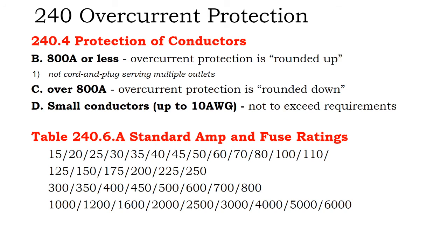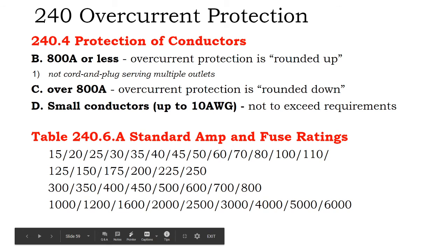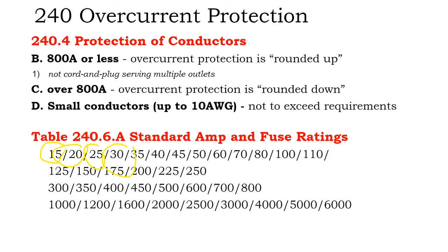For overcurrent protection and breaker size selection, let's say you do your circuit and it's 16 amps, and you go with a 20 amp conductor and you find a 20 amp breaker. That's fine. But breakers only come in certain sizes: 15 amps, 20 amps, 25 amps, 30 amps. So what if you calculate the load and it should be 18 amps, and then you do your 25% oversizing and your conductors need to be 22 amps?